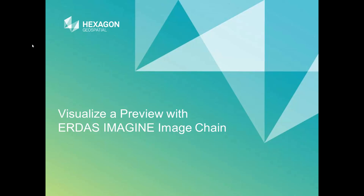Our topic, flexible ways to visualize a preview using the ERDAS Imagine image chain. In this module, we'll generate an NDVI image preview to see how to use the image chain introduced in ERDAS Imagine 2015 to swap display modes from panchromatic to pseudocolor, enabling the preview to be color-coded for easier interpretation.